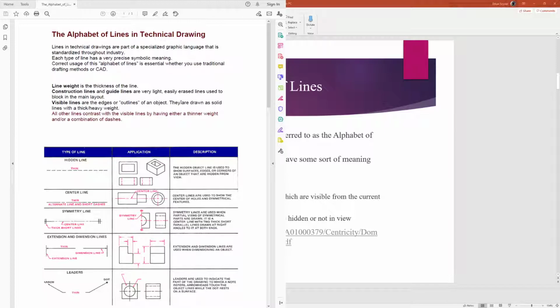A lot of this is regarding the type of lines in the applications. Usually, any solid lines that you see are going to be things that are in your direct view. Anything that's dashed, at least a uniform dash, is typically going to indicate parts of the geometry that you're unable to see. And these can be indicated in technical drawings as well,